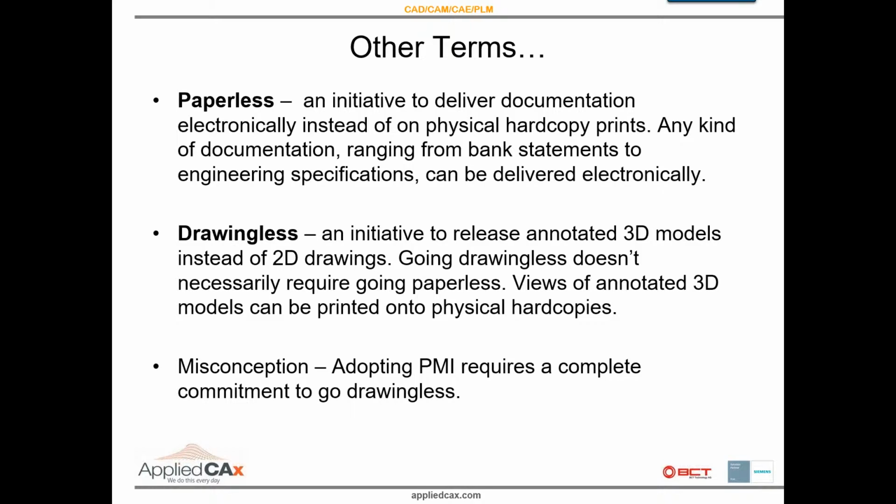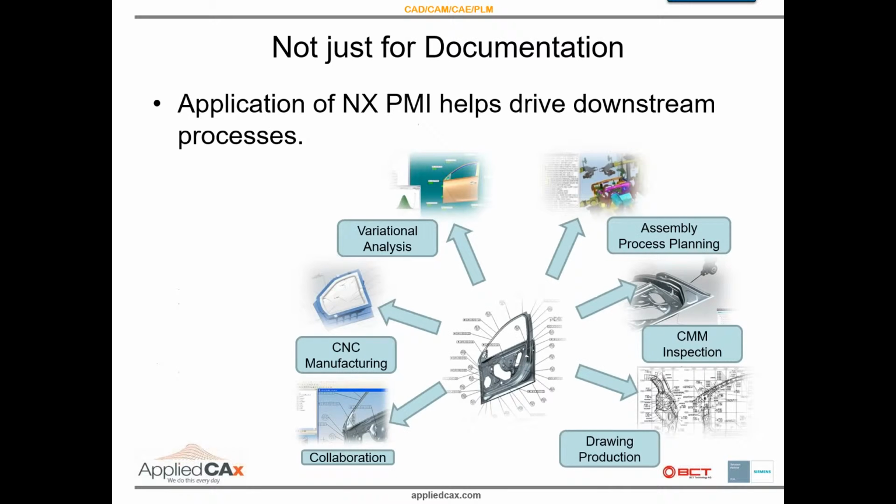Another review of terms. Paperless is an initiative to electronically deliver information, but that information could be a STEP in a PDF, or the CAD file and a drawing file. To go drawingless means that there's no two-dimensional drawing at all. Everything is annotated in 3D models. If you're going into PMI, model-based definition, you do not have to commit to going drawingless. Most companies are going to have legacy data that is a mix of drawings and 3D model-based definition in PMI. Drawings are going to be a part of our lives for a long time.